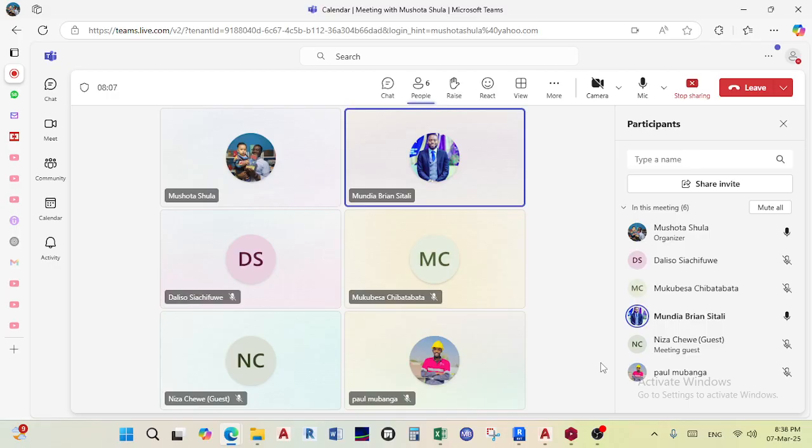So there's a retaining wall that we did there. It's 233 meters long. So you can't do a concrete structure that is spanning all that long. So we had to do it in panels. The maximum length was 10 meters for each panel. But hypothetically speaking, what would happen if we casted it all at once?